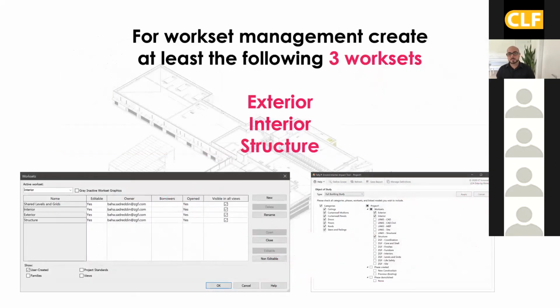For work set management, I think the bare minimal number of work sets to create would be to have an exterior work set, an interior work set, and a structural work set. The structural work set, again, would be the structural model. The exterior would be your enclosure, and then the interior would be anything that goes on the inside. Now, your company or your firm might have a lot more than what we see here. This is just a bare minimal. It's better to have more.